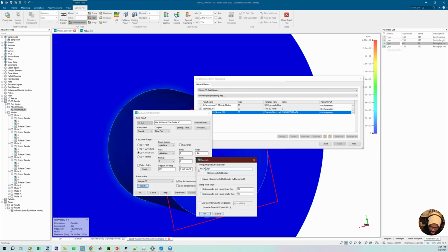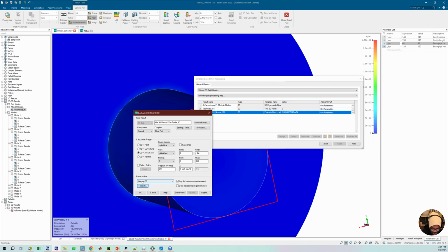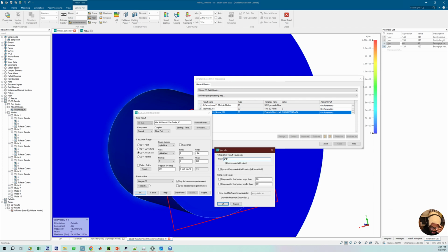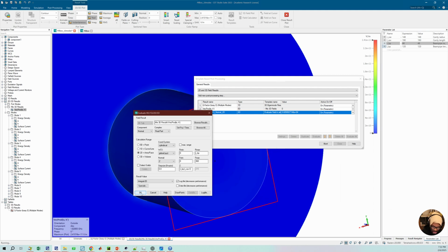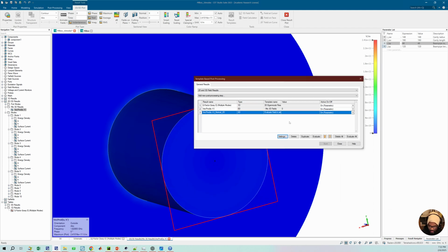But then look at this is f of x. If I click on this, then okay. But what we are doing here is not any function, it's just taking the field and integrating it over this face. So if I solve this, I would get exactly the same answer, because it does not even see f of x. One mistake I've made sometimes is I mistakenly select integral 2D, and then I define a function here, and then when I integrate, I have exactly the same answer.